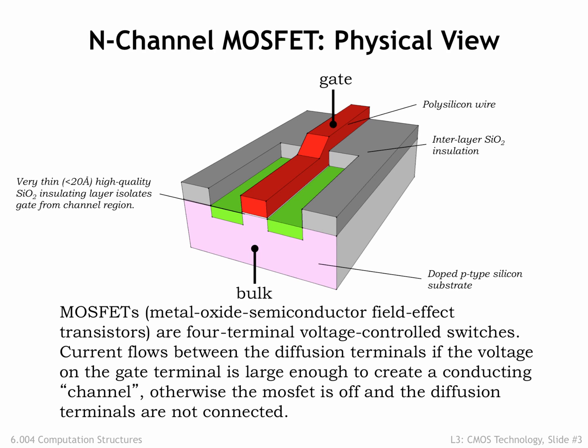The gate terminal of the transistor is a conductor, in this case polycrystalline silicon. The gate, the thin oxide insulating layer, and the P-type substrate form a capacitor, where changing the voltage on the gate will cause electrical changes in the P-type substrate directly under the gate. In early manufacturing processes, the gate terminal was made of metal, and the term metal oxide semiconductor, MOS, is referring